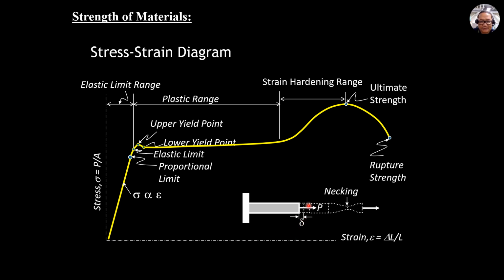So this is the resulting deformation delta within Hooke's law, within elastic limit, and therefore P over area equals E times delta L or delta over L. Therefore, the formula for delta is PL over AE, and take note that P over A is stress, so it may also be stress times length over E. So PL over AE, or deformation due to this normal stress, is normal stress times length over E. So that's it for this part of the slide.